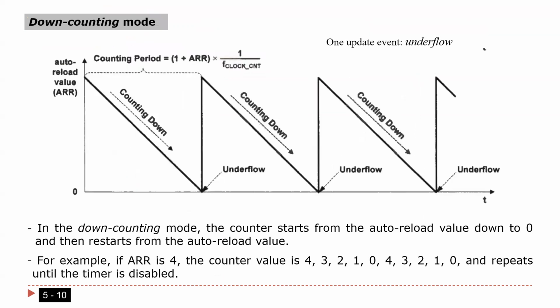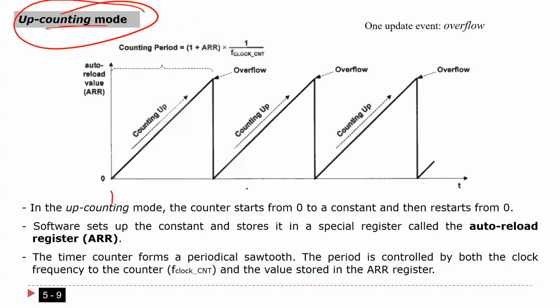Okay, for sure there is a link, but the other way here we call it down counting. As you see here, guys, this one is similar to this one, but the difference is that here I start from 0 and then increment 1 for every cycle, increment 1 until ARR. Once I reach ARR, it's going to go to 0 again automatically. You don't need to do anything. The hardware will do that, okay? And then count again, okay?